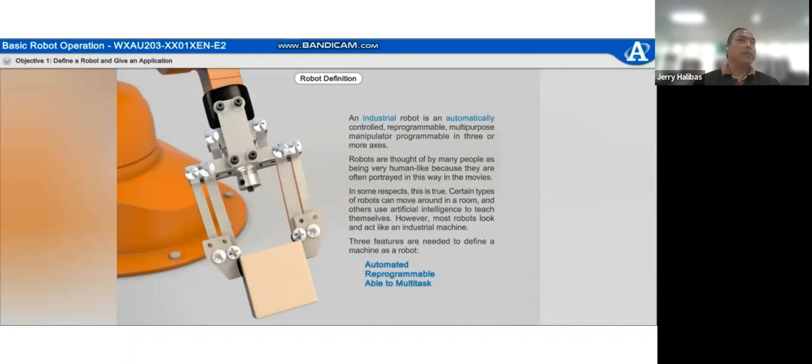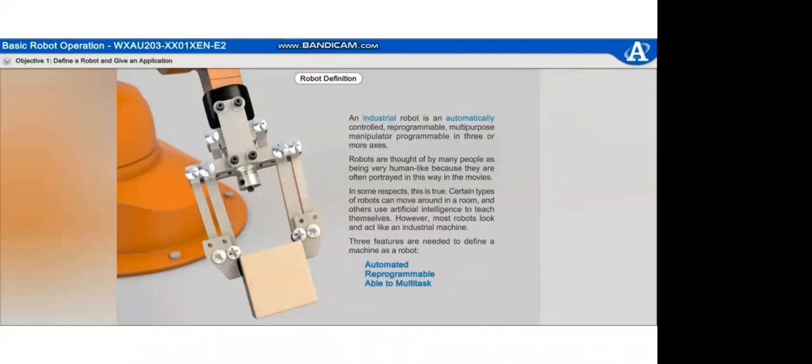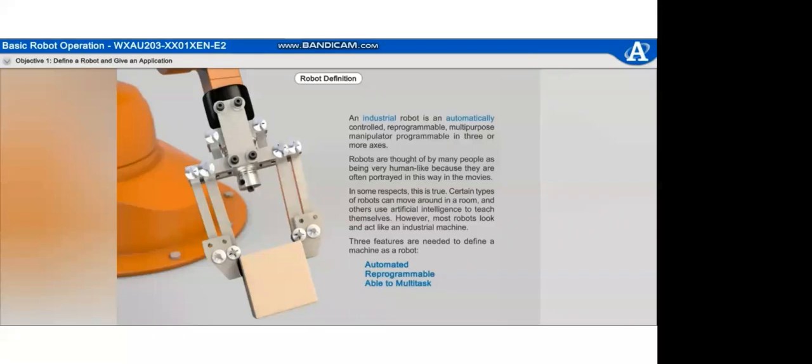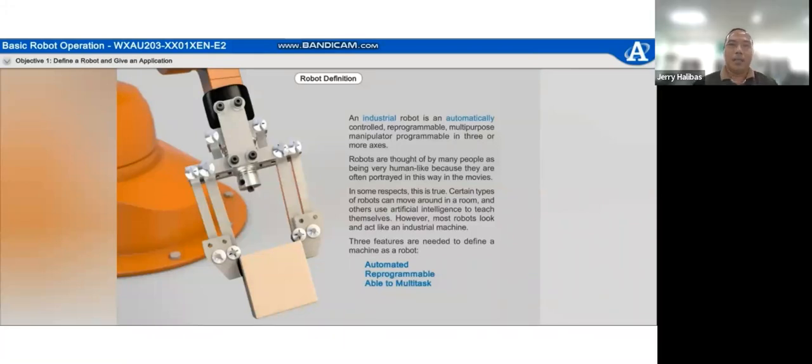In the laboratory, who remembers how many axes you manipulated? Three, sir? No, it's not three. It's more than 3. It's actually 6, the number of joint axes. The axes are the joints, with joint angles theta 1, theta 2, theta 3, theta 4, theta 5, theta 6. So that example is a 6-axis robot. What we said is, it's 3 or more.